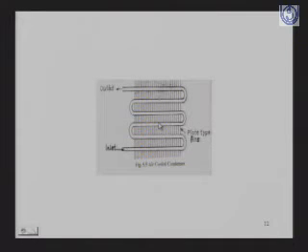Then the condenser. If you recall, the condenser is the unit where the vapors are transformed into the liquid. There are three types of condensers. The first one is the air-cooled condenser. These are the pipes where the liquid refrigerant flows, and these are the plate type fins. This is air-cooled. When the air passes through them, it will cool the refrigerant and it will be converted into the liquid.